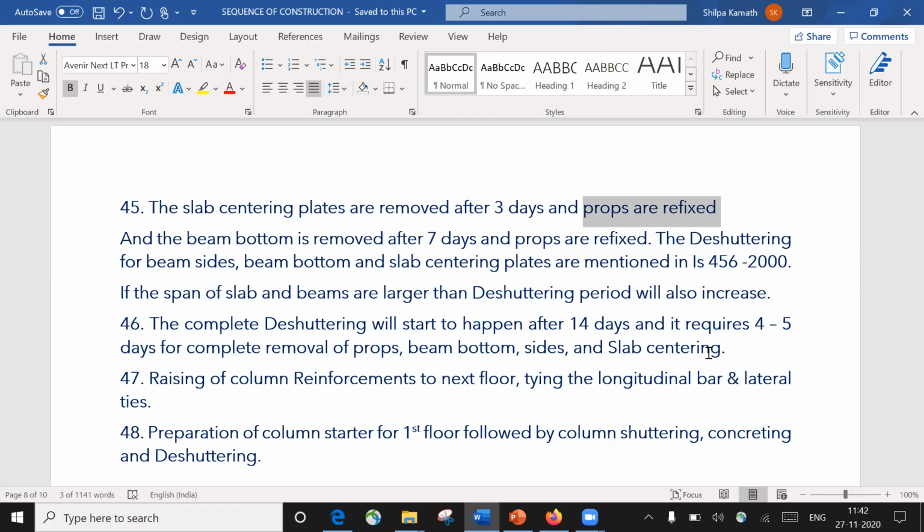So that once you remove all the material from that particular slab, the brickwork persons and the people who make the block work can come and start their work. So let us say you require a minimum of 17 to 18 days for that area to get clear once the slab is casted, right? So next is, once those things are done, again the same procedure will be followed.